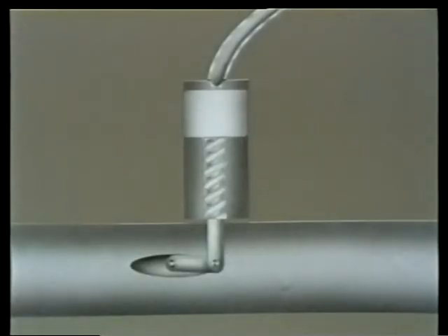Now, on sliding vane and rotary screw compressors, another kind of air-controlled inlet valve is often used to reduce flow when receiver pressure increases. Let's see how it works. The valve itself is within the inlet pipe. It's connected by an external mechanical linkage to a piston in the cylinder. The piston's normally kept in the up position by a spring.